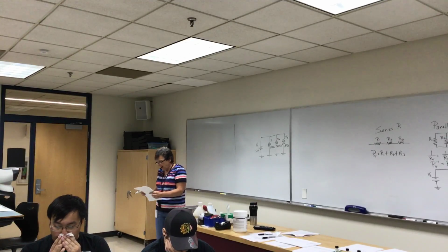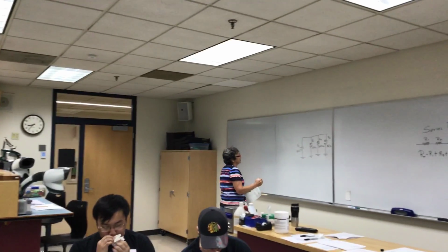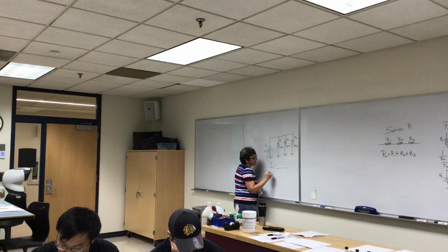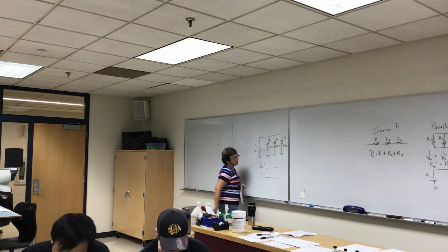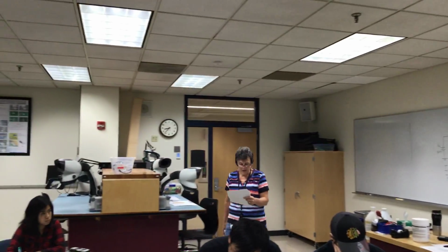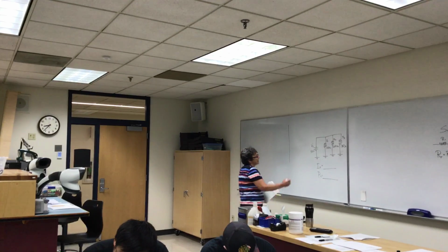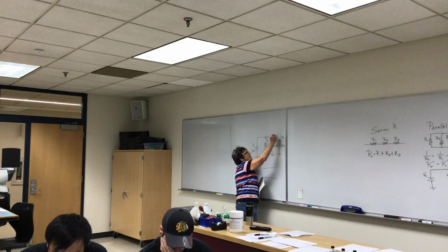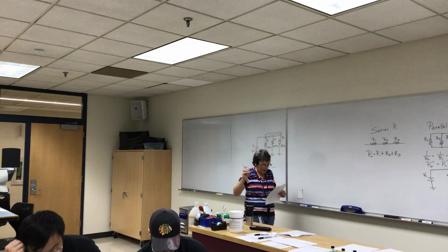What we're going to try and find is our total current and our total power. Those are the 2 components we need to find to do the analysis on this circuit. We know these are in parallel because they're all connected here at ground, they're all connected at this node, and they're all connected at this node. They're all connected together at each end, so they're in parallel.